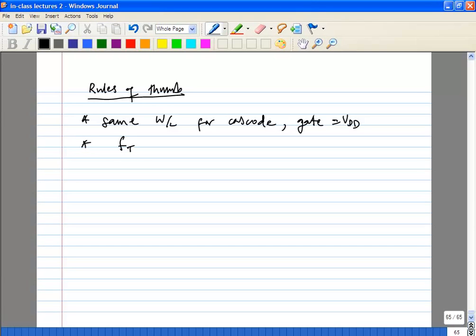And last week we saw you are going to choose W opt and power consumption, so you get some FT. It's a good rule of thumb, because we saw that at around 10 times f naught for the power constraint optimized width, your noise figure is around 2 dB, 1.9 dB. So this is a good point to start. Try to start off with somewhere around 10 times f naught. If you start off lower, you'll probably have a much higher noise figure.